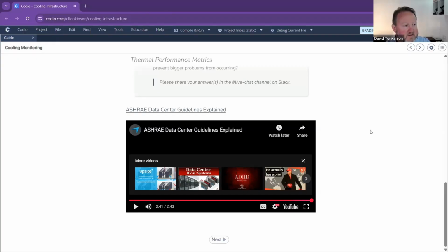One question I should probably ask is what a dry bulb temperature is. Don't know if anyone really cares about that or not. It's an important measurement. Dry bulb temperature is the temperature of a thermometer that is shielded from other heat sources such as radiation or another light source. Essentially it's a shielded one, so it's not exposed to water vapor or to direct light. Think of it as a thermometer in a dark box.